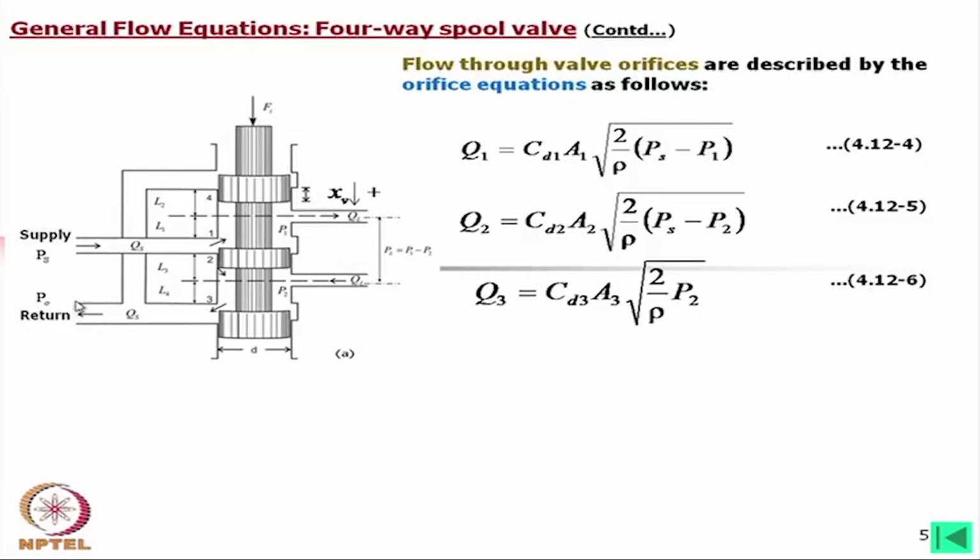So, what you would do, your Ps should be 11 minus 1, which is equal to 10 megapascal, whereas P0 is equal to 1 minus 1, which is equal to 0. While we are considering this pressure and this pressure, we first consider that. So, P0 we put as 0, and Ps is the differential pressure between these two. That is why the equation is in this form.